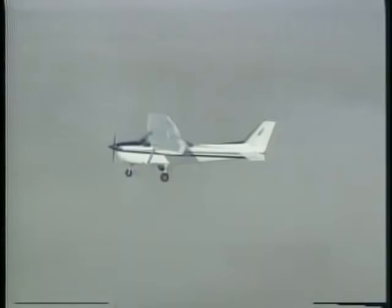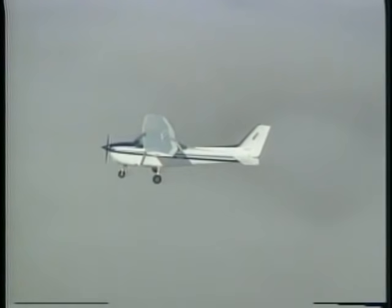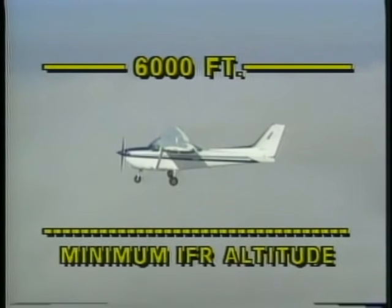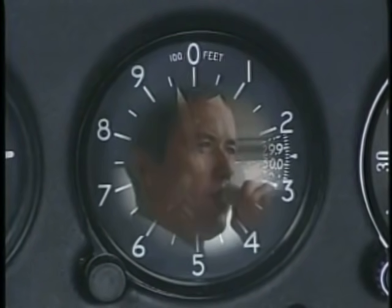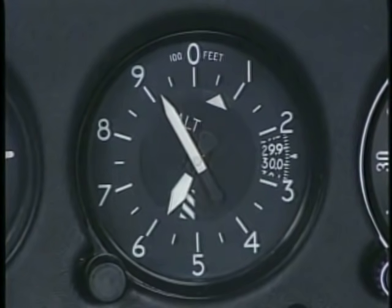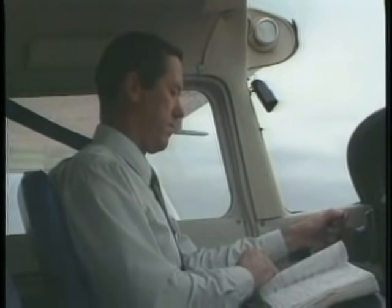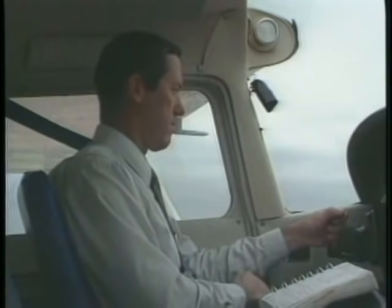A cruise clearance authorizes you to climb, descend, or cruise at any altitude between the assigned altitude, 6,000 feet, and the minimum IFR altitude. You are not required to report altitude changes to ATC. However, once you do report leaving a specific altitude, you cannot return to it without ATC authorization. The cruise clearance also allows you to use any approved IFR approach procedure at your destination.